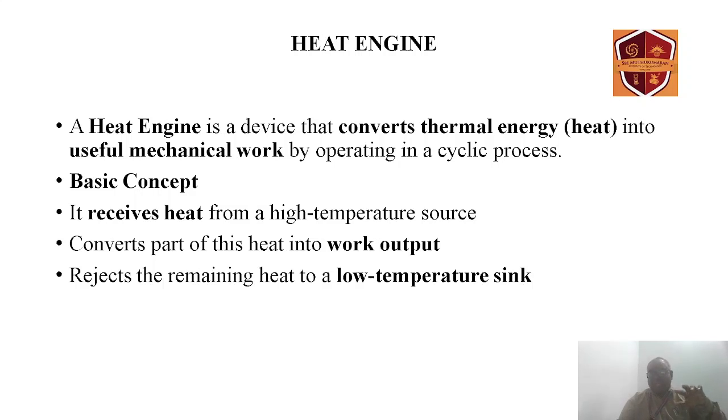The energy is transferred initially. The chemical energy of the fuel is converted into heat energy, and the heat energy is converted into useful mechanical energy. That is, it receives heat from a high temperature source and converts part of the heat into work output. It rejects the heat energy that cannot be converted into useful work. Some part will be rejected as heat. That follows the first law of thermodynamics, that is Q is equal to W, the net work transfer equals the net heat transfer.